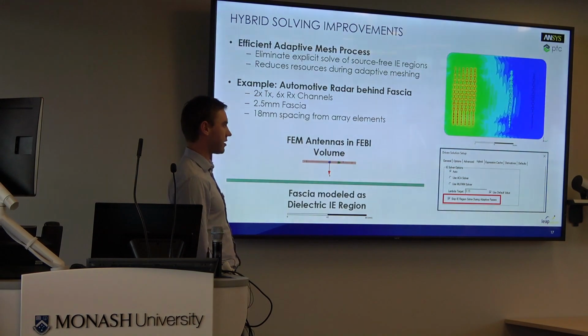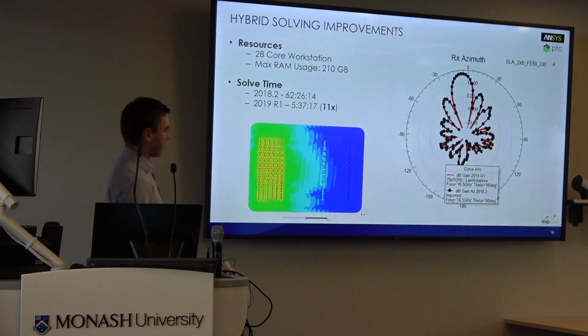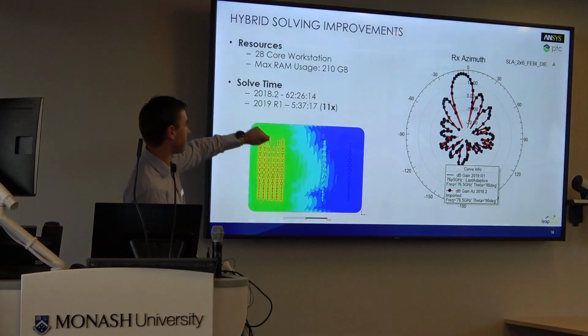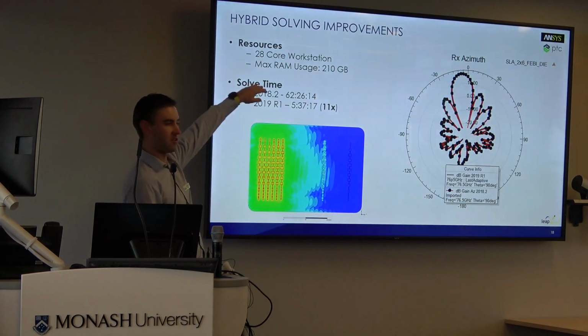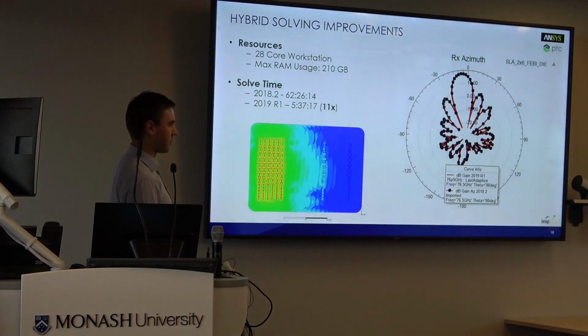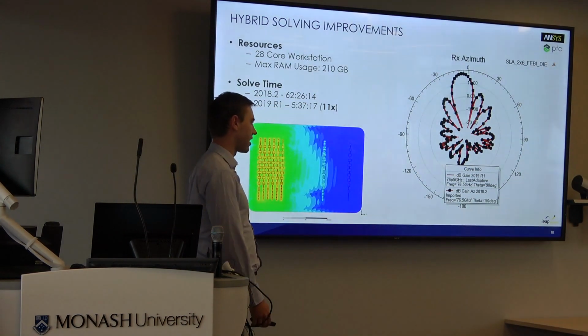If we look at what that looks like in practice, the radiation pattern is almost identical, except that now instead of taking 62 hours to solve, it takes just under 6 hours. That is purely by cutting out the extra IE solve.